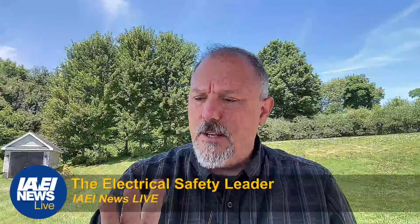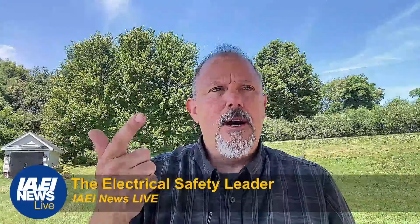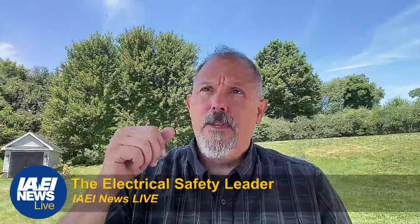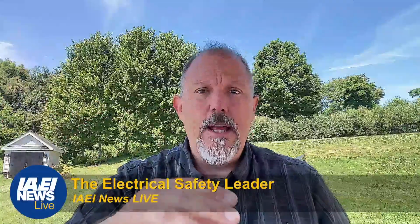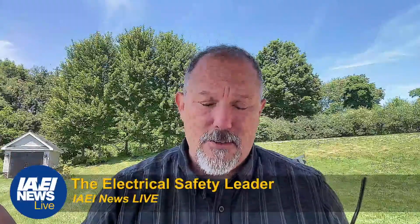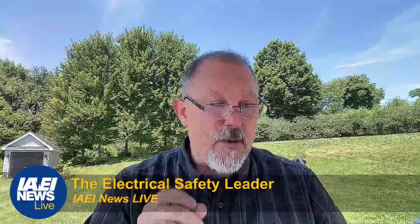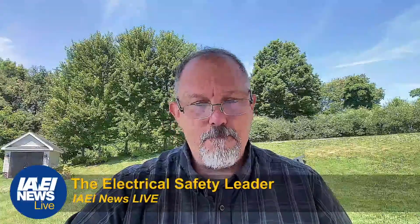electrical. So if you're in a data center and you've got backup UPSs, you've probably got a lot of double-ended switchgear, multiple ways to supply power to equipment because they want to increase the reliability of that installation. So when you have multiple sources, multiple options to energize a piece of equipment, as an electrical worker, as the owner, as the foreman on the job, as the designer, you need to make sure we all understand what it will take to establish an electrically safe work condition. So the single line diagram plays a very important part in this whole topic of lockout tagout.